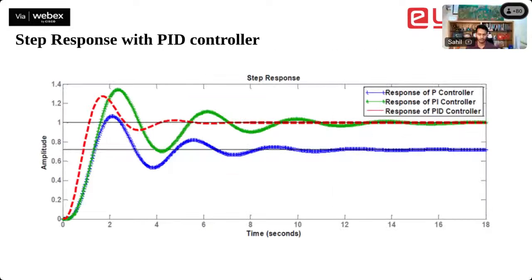Now coming to the performance of this. Let's understand two important concepts here: step response and steady state error. Step response is how a system reacts when you suddenly change the input, like flipping a switch from 0 to 1. For example, imagine asking a robot arm to go from 0 to 90 degrees instantly. The arm accelerates, overshoots, oscillates, and eventually settles. This shows the step response behavior.